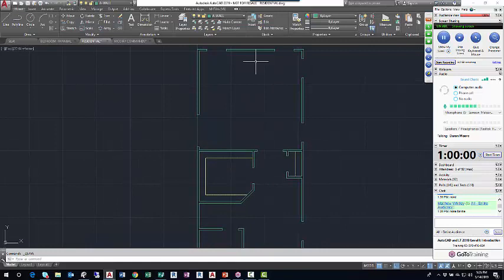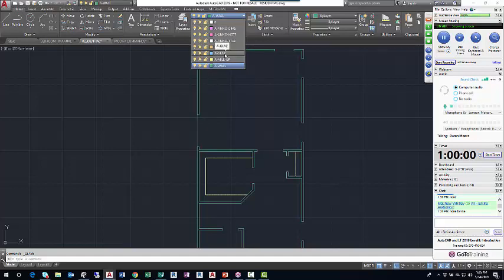So I've been working on walls, and so have you. And with the exception of these shelf lines, everything that I've been working on has been a wall on the A wall layer, ironically enough. So now I'm going to start inserting windows, and I'm going to change layers. Now this is kind of like code almost, but the window layer is A glaze, architectural glazing layer. I mentioned that glazing is a category of building material, so that category of building material lent part of its name to this layer name.